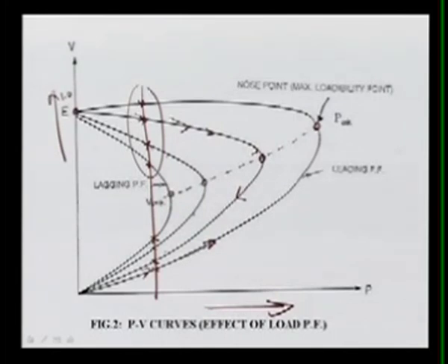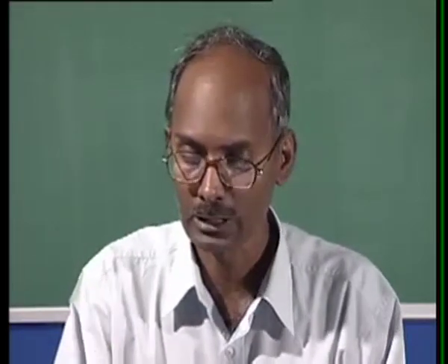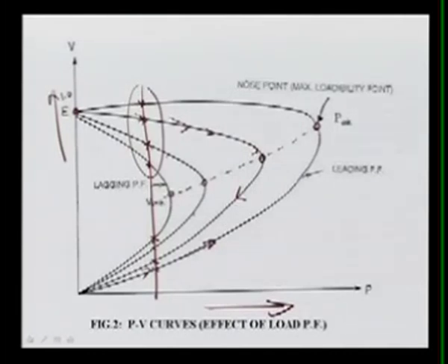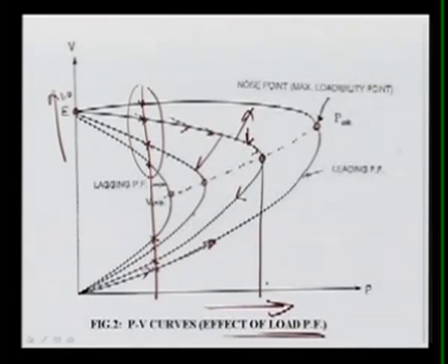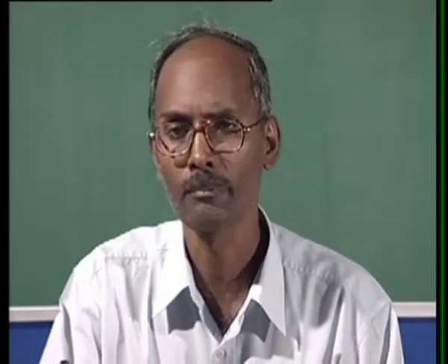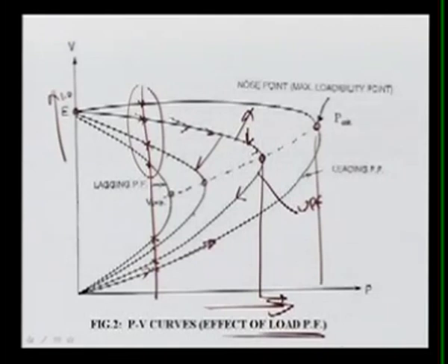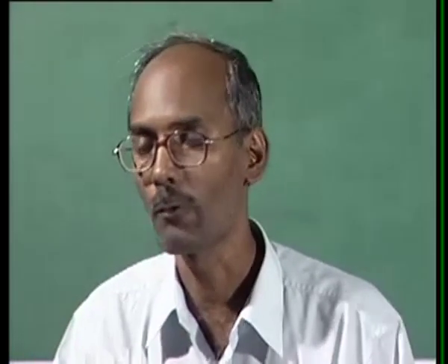Again, with changing the power factor, means the reactive power support at that bus you are changing, you can see this value keeps on changing. So this is the effect of load on the power factor. We can say if it is a normal unity power factor, this is your lagging. If you are leading the power factor, you can again have more loading. So at this point, suppose your power factor is unity power factor, UPF, you cannot load more than this. So in this case, to load more you have to go for some leading power factor, or you can use some reactive power compensator, some reactive power capacitor, etc. Then you can go up to this point and keep on increasing. So you have to have a better power factor to avoid the instability.